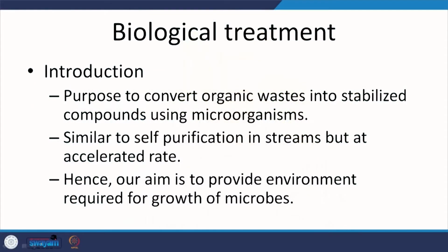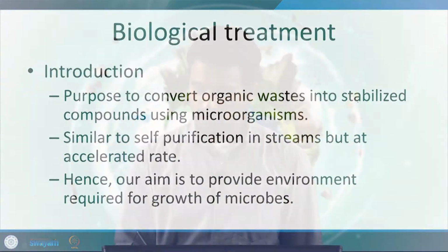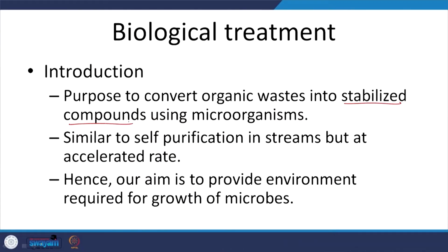So biological treatment, what are we trying to do? We are trying to see to it that the waste, which if I leave it out there, can lead to septic conditions, smell because of reduced forms of sulfur like hydrogen sulfide being given out. Explosive gases like methane can be given out, and then you are going to have flies and such because of septic conditions. So you don't want to have that. You want to have a relatively stable compound, and we are going to get to that by using microorganisms which release enzymes. Again, our main aim is to degrade the organics, by promoting the growth of microbes, right? So let's move on.